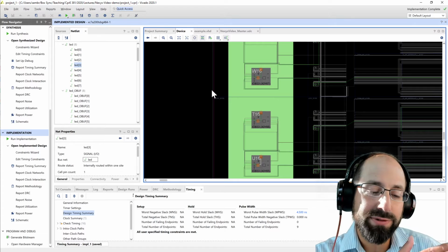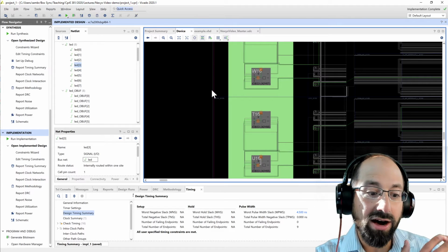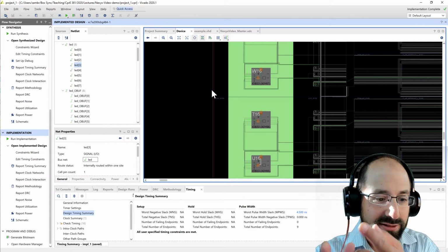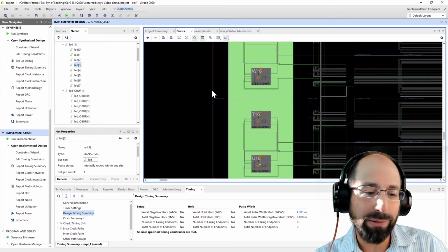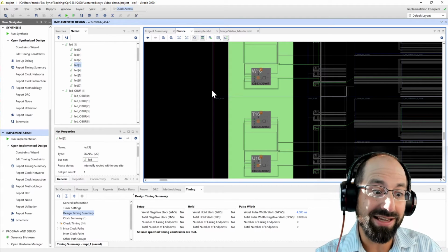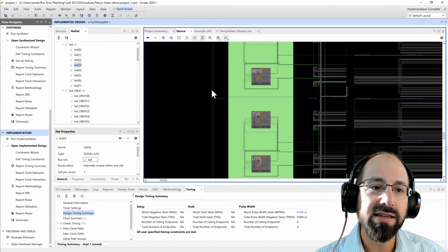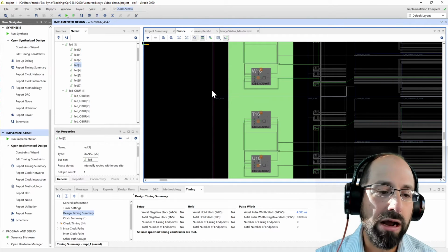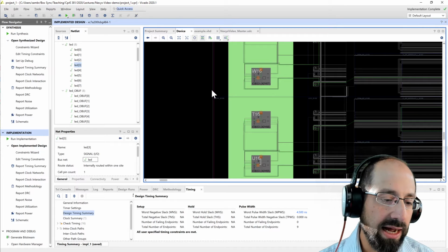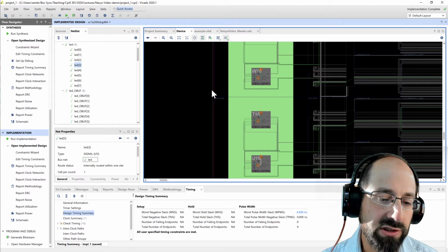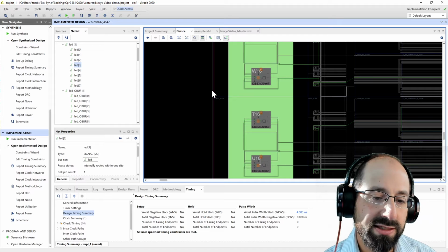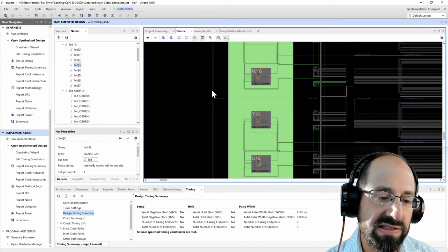There's a lot of abstraction in your VHDL, and then the underlying implementation, and even this is still just a model. This makes certain assumptions about temperature and things like that, and your critical path can even change based on transport delay of individual wires. But that actual physical placement and routing has a really big impact on the resulting critical path of your design, what clock frequency you'll be able to run this correctly in your design.